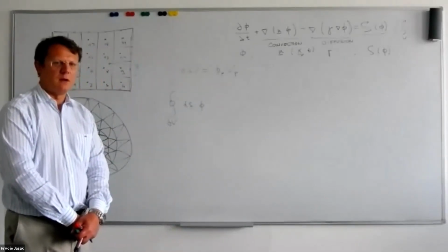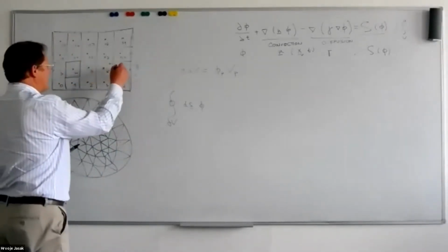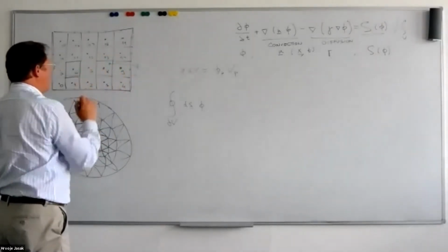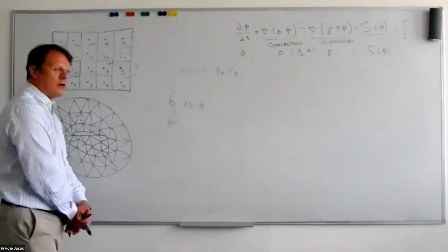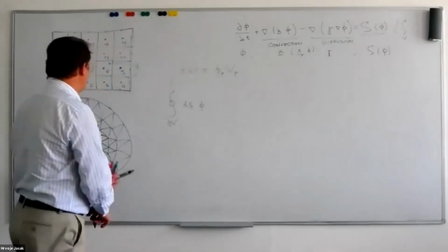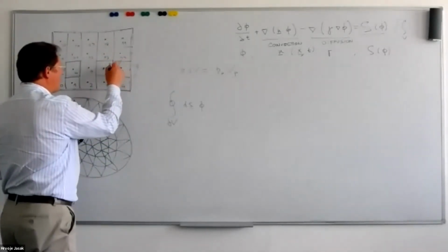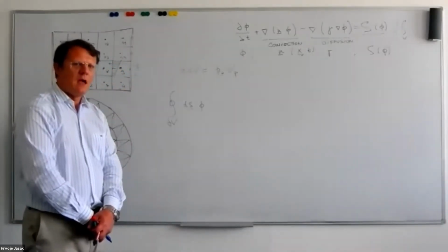The first problem is that I have the value in the cell centers, and in order to evaluate the integral over that cell, I need to visit all of the four faces of the cell. Fortunately, I can also postulate linear variation of my function across the face and play the same game.